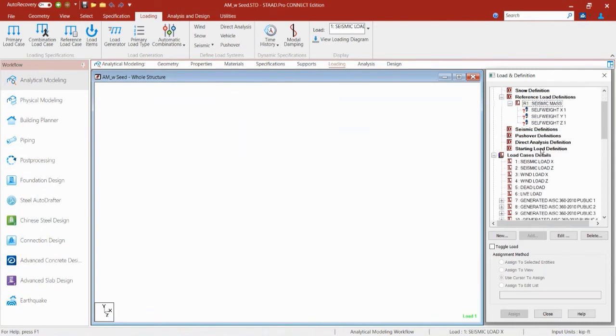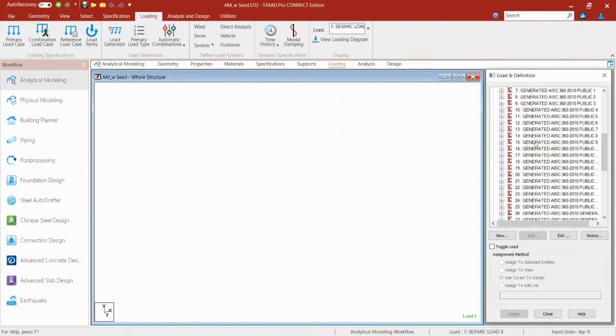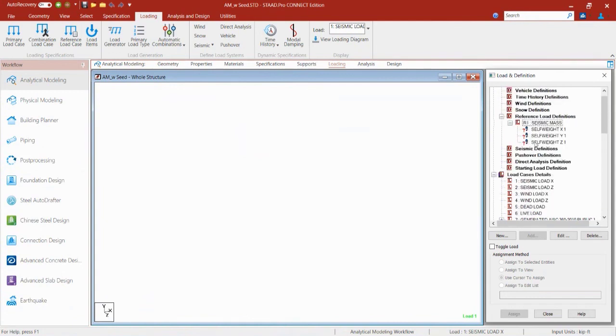So here I'm ready to go. I did it for this particular model since we have a loading focus today. I used this to create some load cases. I actually yesterday created a sample model where I put in perform analysis and change command after each of my seismic load cases, and then that came in correctly. So that was kind of cool.